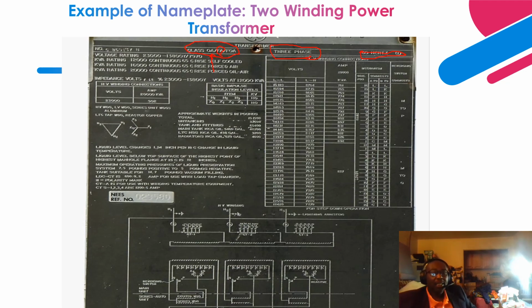Then also it has forced air, so you have second stage fans that come on. So you have two-stage cooling fans that come on at this stage. Then you have a pump that comes on to remove the heat faster because the transformer has picked up bigger load. As you can see over here, we'll walk through the MVA rating at each stage.